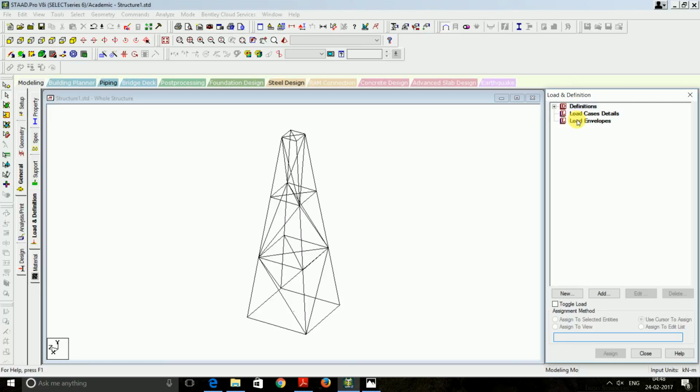Basically, wind load acts on all the members from windward face as well as leeward face. We are just going to consider windward face. And for that windward face also, I have calculated the wind forces which will act at a node. Basically it will first act on a panel, then it will get distributed on the members, and then finally it will act on a node. So I have simplified that for you people. I have calculated all those and I'm just going to apply it.